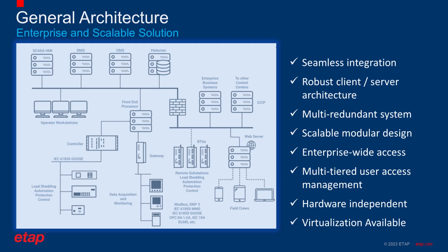Given its interoperability, the system communicates to various hardware independent of the brand, including meters, controllers, RTUs, gateways, protection relays, and more. With this, we get a seamless integration. We have an application called the SCADA integrator that allows us to map from a library of components to the different meter relays and devices.